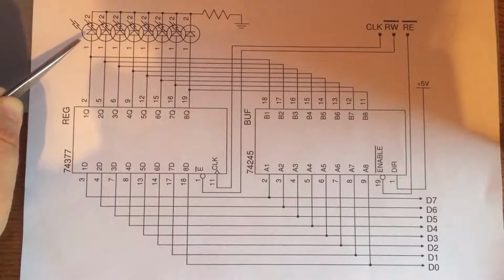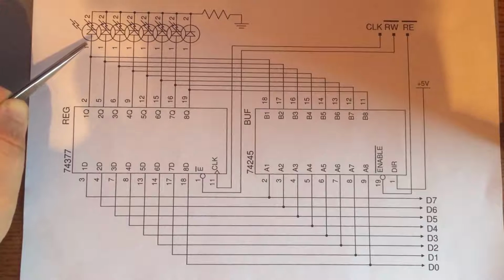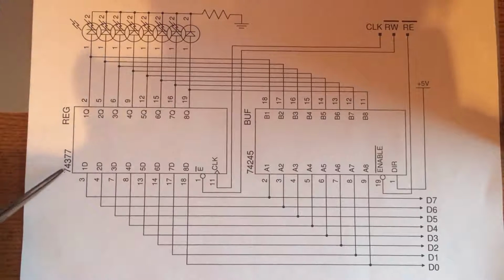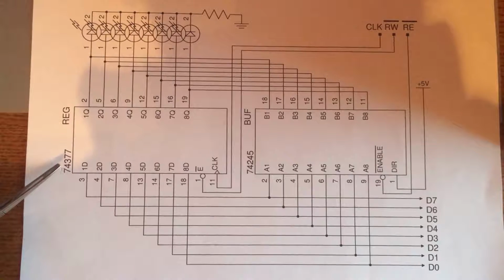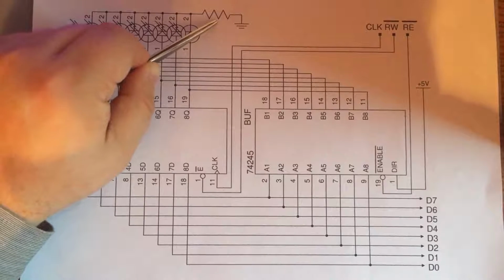And remember, I have 6, and I have an ALU, and I have control signals, and I have RAM. So for a single register to draw almost half an amp meant I was looking at a computer that was going to draw 4 or 5 amps. And in addition, sending 50 milliamps through an LED permanently didn't seem like a very good idea. So in contrast to the LS series of chips, the one disadvantage of using the HCT series of chips is that I need current limiting resistors for my LEDs.